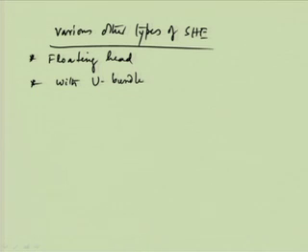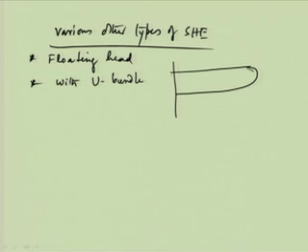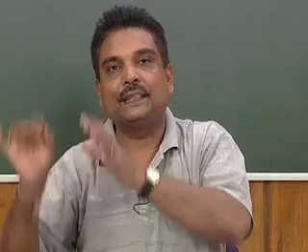That means tubes are coming like this in a shell and tube exchanger. So tubes have a U bend in the shell and tube heat exchanger, and they are fixed with a tube seat. This is the tube seat, and this is the tube with U bend. So, this kind of heat exchanger is also there, where the bend side is a floating kind of thing.